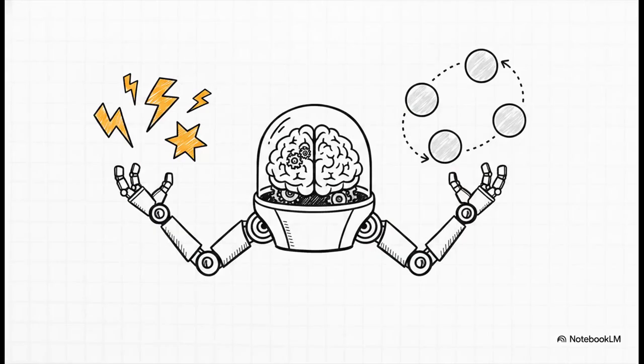So, a quick summary of the model. Real-time systems are inherently reactive. We architect them using the stimulus response model so they can manage a continuous, steady flow of predictable periodic sensor readings whilst remaining completely ready to instantly handle unpredictable aperiodic interrupts. Doing both of those at the exact same time requires concurrent processing, which perfectly sets up our next topic.